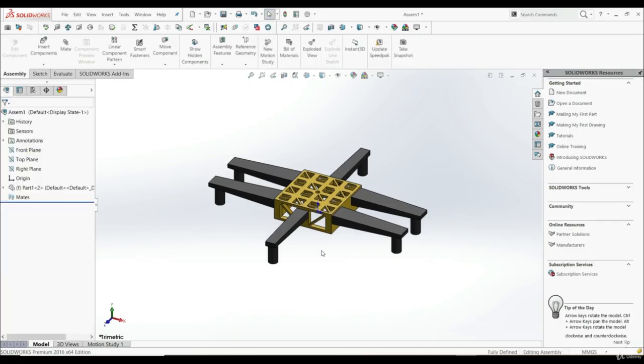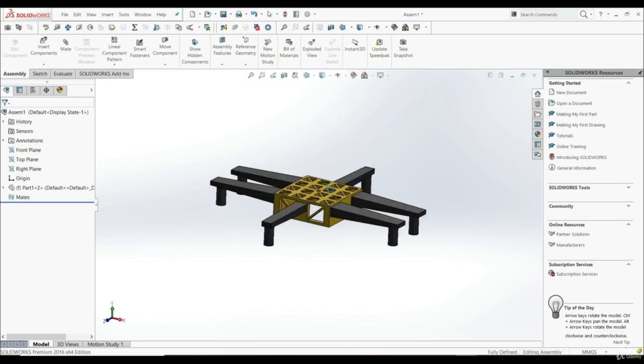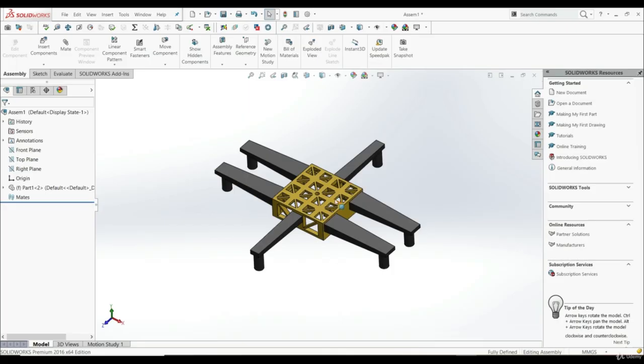Now you don't have to define the Coincident relation separately. And now you know that your part is fixed to the origin. Now you can turn off visibility, and this is it. And now you can insert Part 2, 3, and so on.